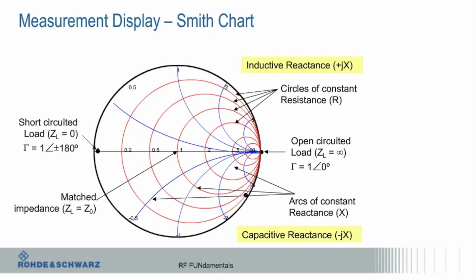Broadband matching is another challenge. You basically have to do stages of it, and that's a fairly complex topic. But in principle, what I just mentioned would be at a single frequency. To do a broadband match, you have to make some trade-off between the frequency ranges. So if you want more on that, I could definitely give you some material.